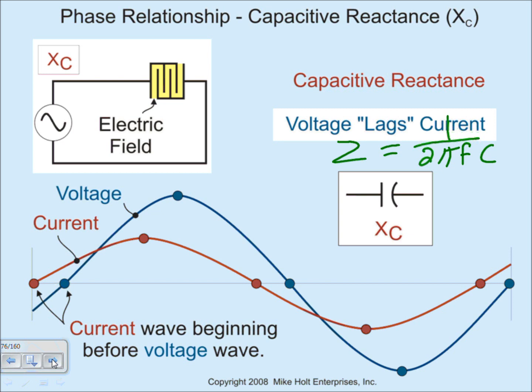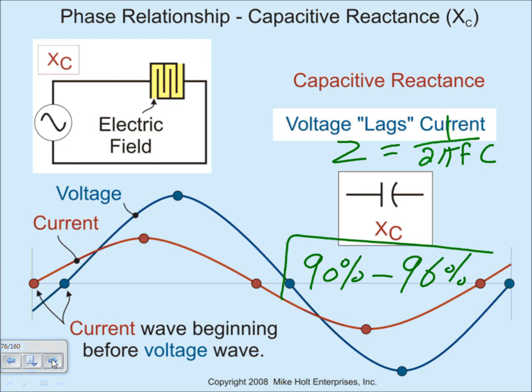What happens if you have a lagging power factor? If you plug in here, instead of getting 120, you're going to get 100. Also bad news, right? So leading will make the voltage higher, which is bad news. Lagging will also make the voltage lower, bad news. So you're going to find this optimum design. You want your system to operate, for the most part, between 90% and close to 96%. That's where you want to be.